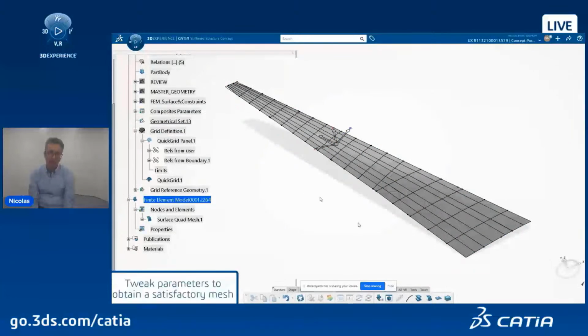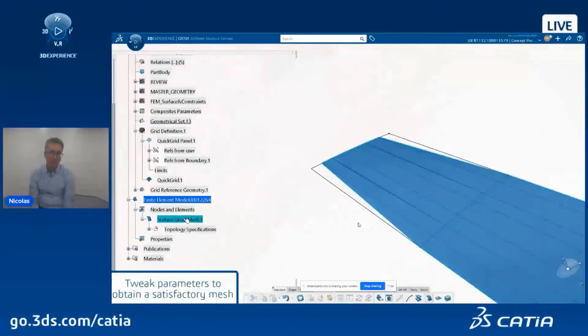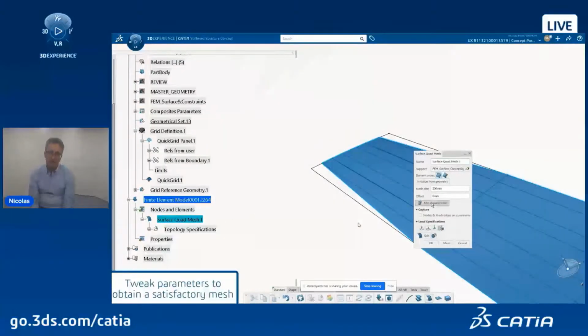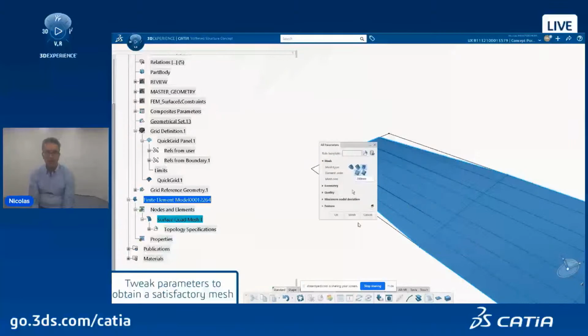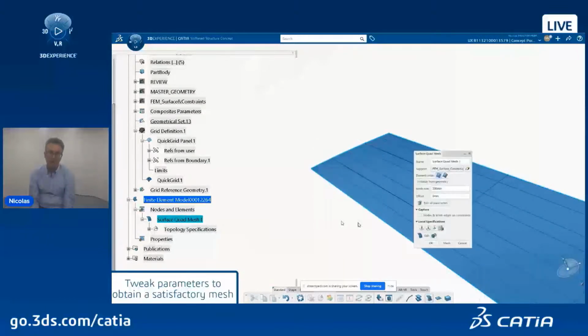Here you can notice that on the tip, with the mesh size we have taken, some simplification is done automatically, so you can go ahead and edit and make sure you do not simplify your geometry and that you have elements going everywhere.